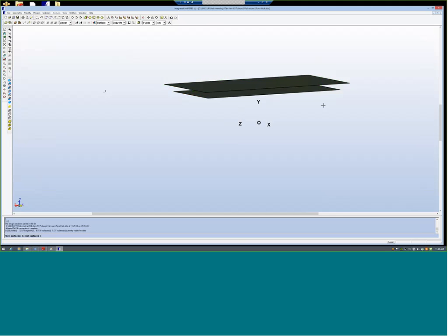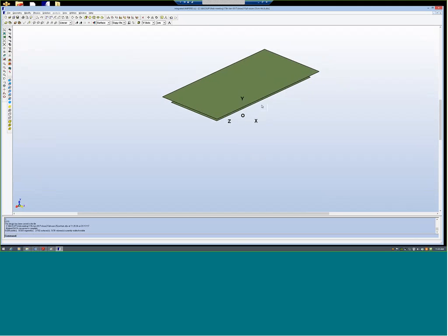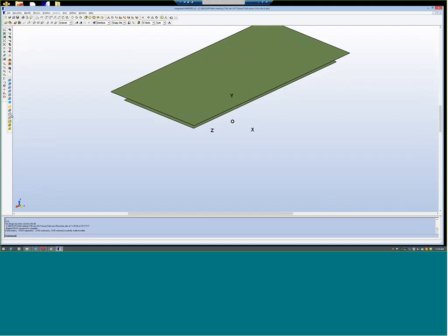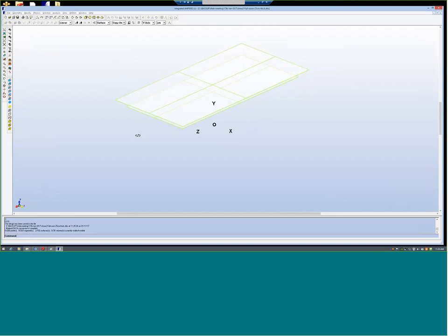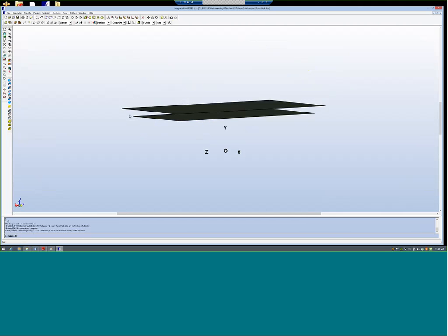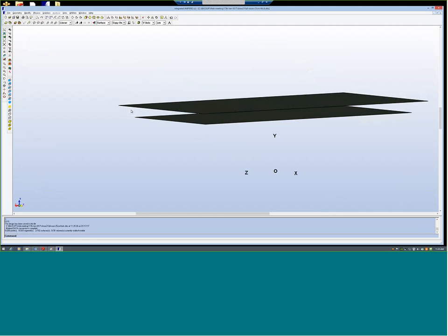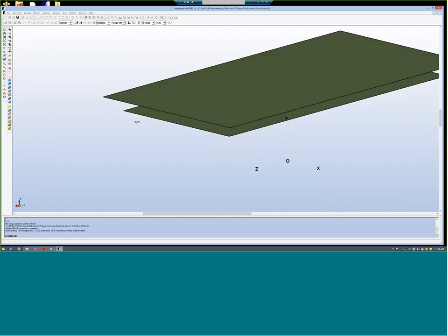Okay. Now these are the 2 surfaces, you have to mesh them. Thing is, these 2 surfaces, one looks big, another looks small, because the reason is the thickness I took it as 25 centimeters. Suppose imagine that if the thickness is only 1 centimeter, I think the bottom surface would be as big as the top one. So that means whatever mesh we put on the top surface, we can put the same mesh on the bottom surface also.